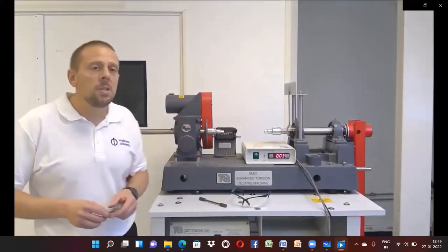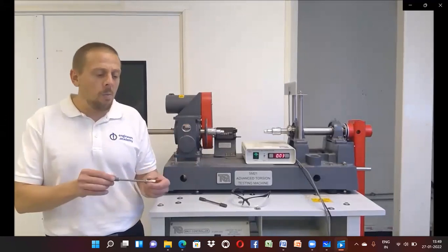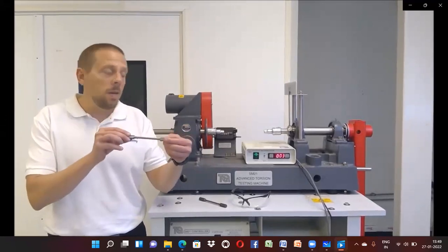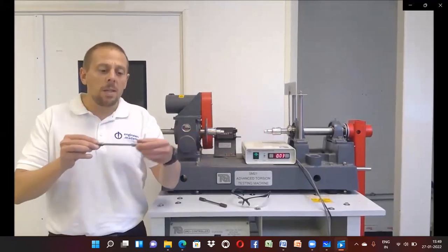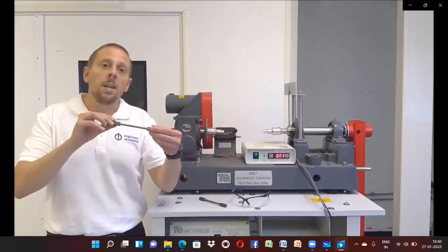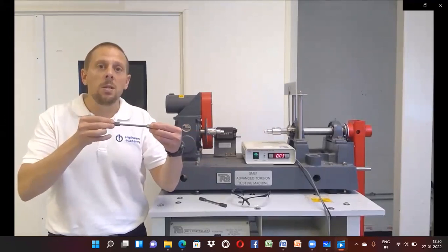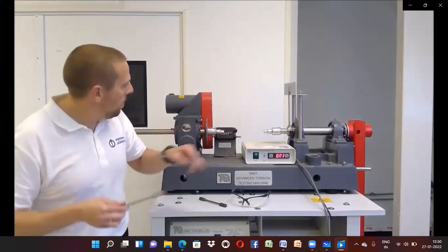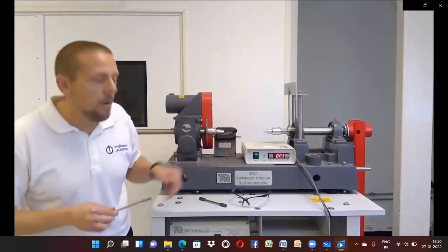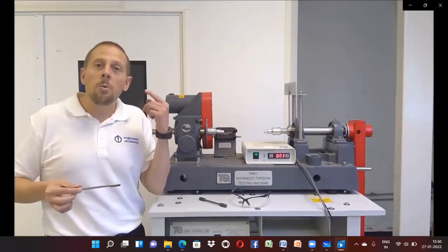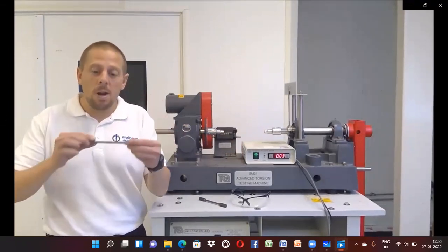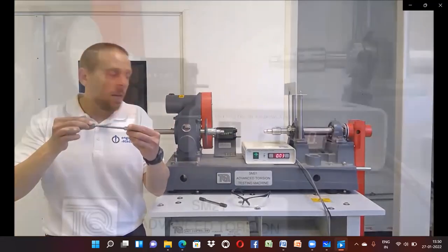Now, the machine that we have here is the torsion tester, and basically what we do is we load each test piece into the machine between these two chucks. Now, when we begin the test, one end of that test piece is going to be twisted or rotated. We have some information on the display here around how much that has been twisted by. The machine actually has an audible click, and every time we hear a click, the piece is being twisted.